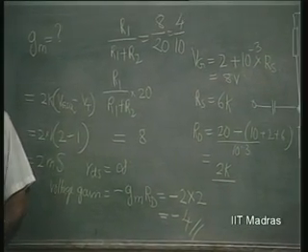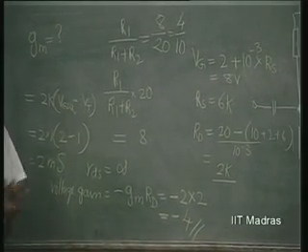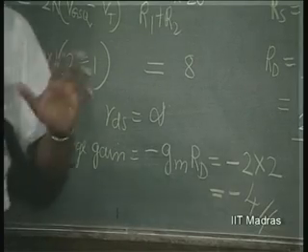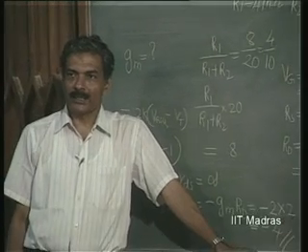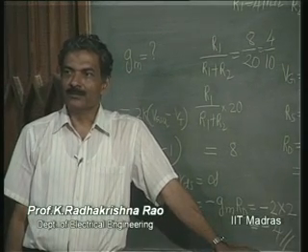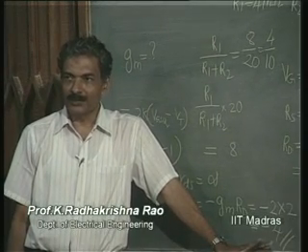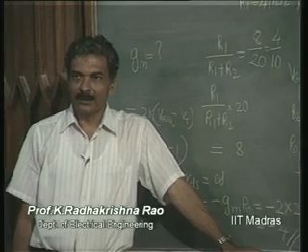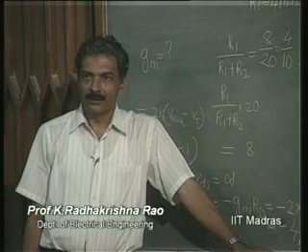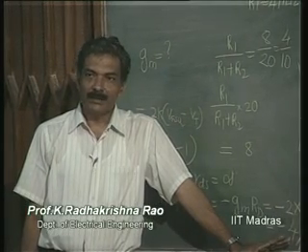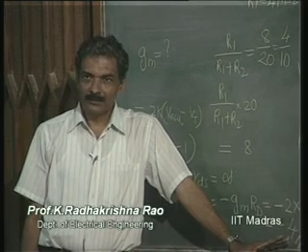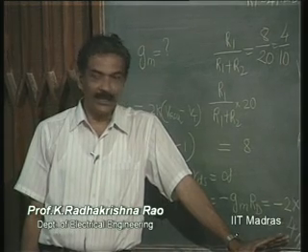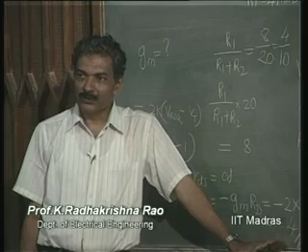I had warned you that gm of a comparable dimension bipolar junction transistor will be of the order of 40 millisiemens or so at 1 milliampere. Whereas gm of this is only 2 millisiemens, and therefore correspondingly the gain is pretty low.